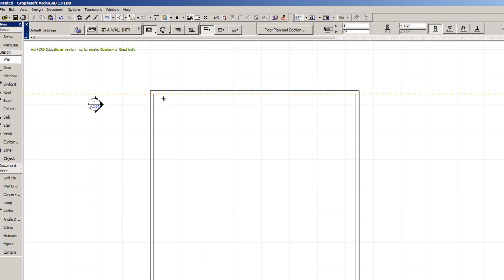And now all I have to do is, I want it from this side, so I'm going to come back over here. When I get over that hash mark, the check mark will show up. It'll snap there, so I'm going to go ahead and choose my start point. You notice I'm in the wrong mode. I don't want a rectangle. So I can come up here, push and hold that button down, and I want multi-segment. So I choose that. Now it gives me a segment.